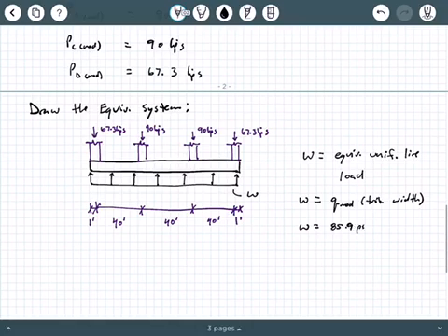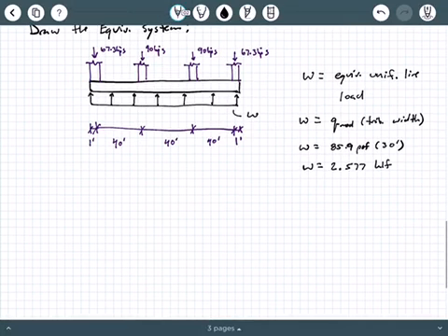So that's the 85.9 PSF times 30 feet, and let's punch that through. 85.9 times 30 feet. If I go to KLF, I get 2.577 KLF. Or you can get 2,577 PLF, but it's a line load, not an area load. So it's kips per foot.